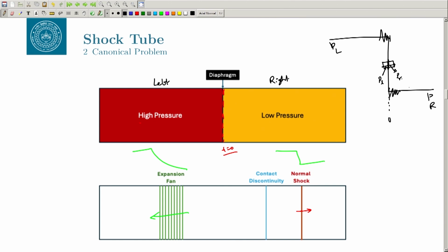So, you have to have some kind of dissipation which can smear out the shock. The shock may be happening in a very small region, but your numerical scheme will smear this out, and then your shock is happening in this thick region, let us say between this line, and it tries to predict the shock like this.